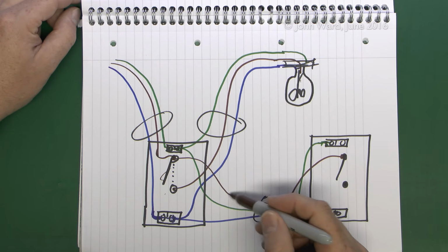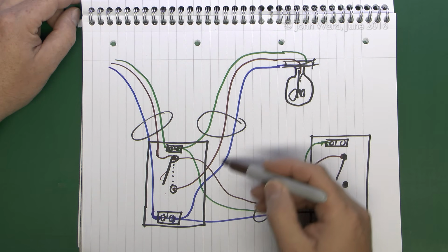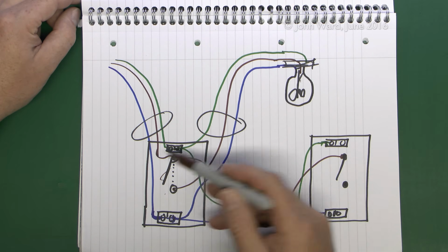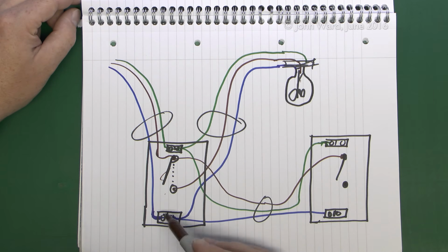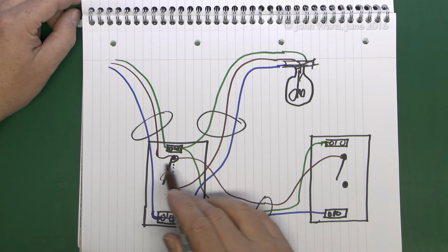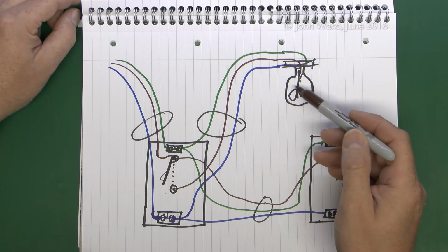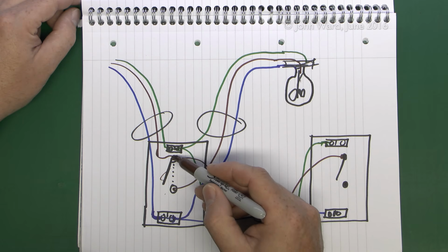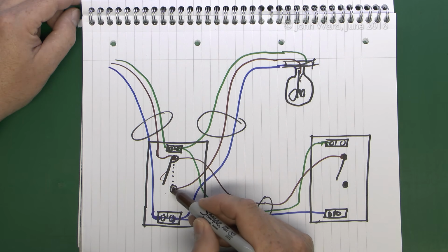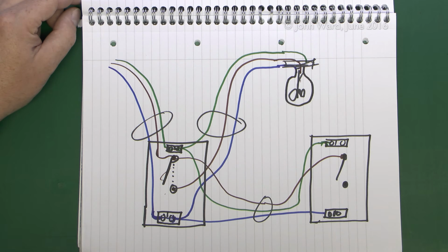And you need to make sure that the cable here, which goes to the light, is of course identified separately from the other two, because these two really are just connected together. Neutral straight through, line straight through there, and the earth straight through. It's only the one going to the light, or the item we're actually turning on off, which has to have the break in it, so we're connecting that to the other terminal of the switch.